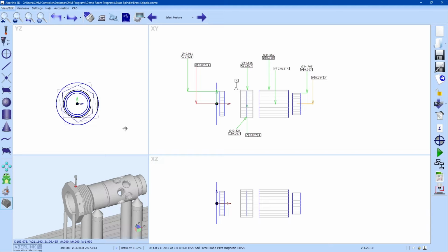And as you can see, you're getting a nominal, repeatable, more robust program by verifying runout, as it's aligning all the dimensions through datum A, so through this axis alignment, and then it's essentially running the clock along the entire outside profile. So it's not only taking into account the axis alignment, but also the form of the shape.